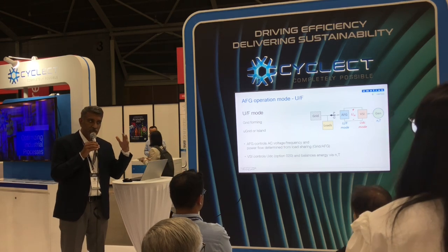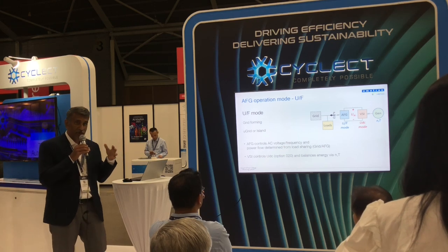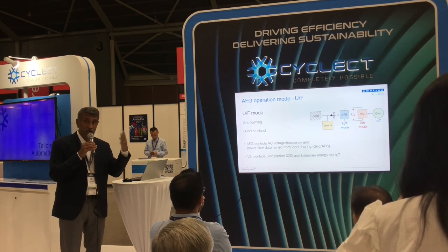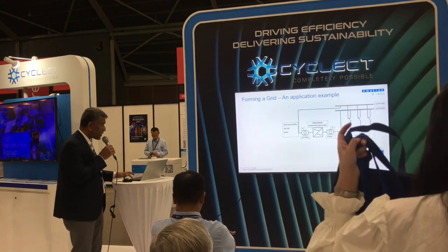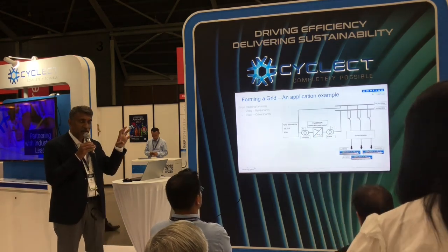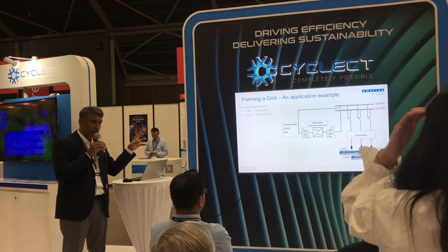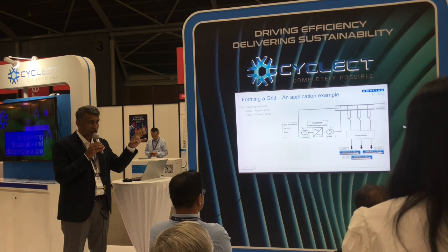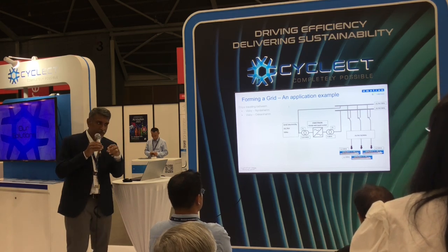Traditionally, they've been using generators to generate the 60 hertz. But nowadays, you have a lot of environmental clauses which say that you cannot use generators, you cannot pollute the environment. So then what we have done is, we have created a grid converter application where you convert this 50 hertz to 60 hertz and you create now a grid by yourself and supply it to equipment.